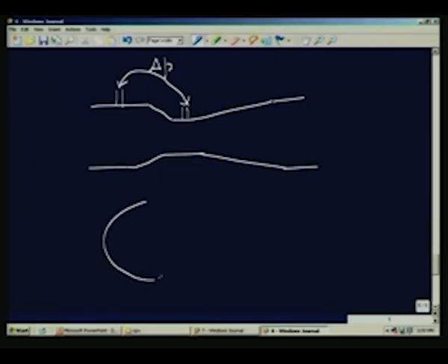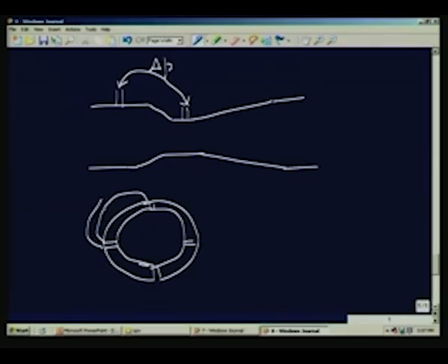So, you have the pipe here, I have taps. So, this is the pipe thickness, I have several taps. That means that the pressures are all communicated to the same port, and that means that I am going to measure the average of the pressure in the 4 taps, in this case 4 or more than 4.